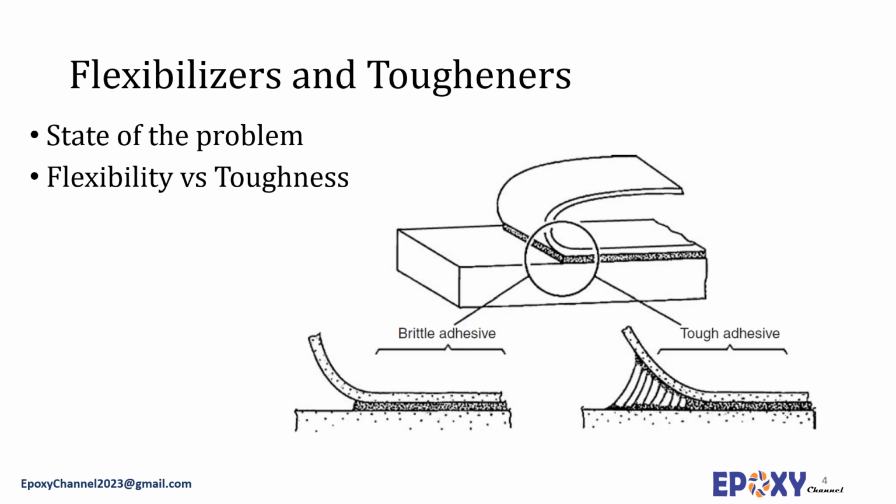Toughened adhesives tolerate damage by preventing crack growth and thus limiting the damage area. This results in enhanced fracture, impact and stress resistance with minimal change in the crosslinking density. Tougheners result in both features: resistance to impact while maintaining a high degree of temperature and chemical resistance.